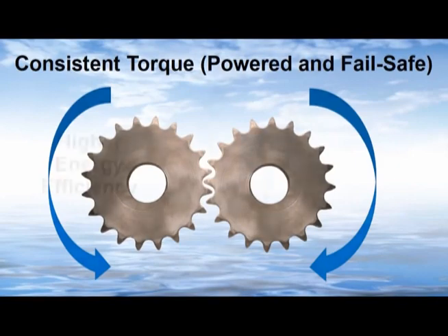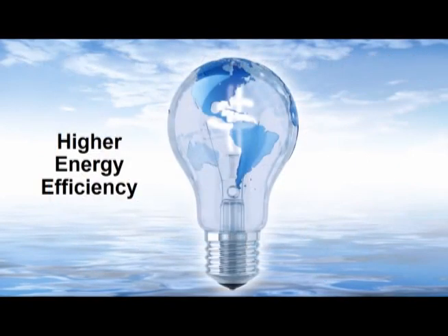Although they have higher peak initialization currents, capacitor-driven actuators provide overall higher energy efficiency. Spring return actuators require extra motor torque to overcome spring resistance on every cycle, and they consume much more power just to maintain a stationary position.